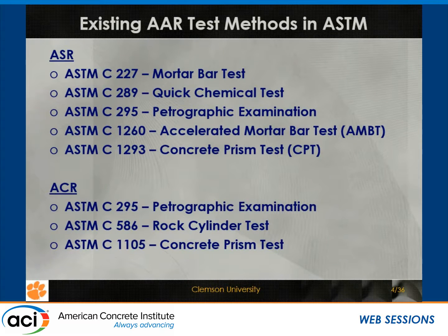And certainly the mortar bar test, which is a faster test, but you have issues with crushing aggregates down from coarse aggregate size to fine aggregates, and doing that, you change the reactivity of aggregates dramatically. Most of the aggregates, you tend to increase the reactivity with a decreasing particle size. But there are certain kinds of aggregates that actually show the reverse trend, where with crushing it finer, you lose the reactive component and you end up less reactive with crushed material than the coarser material. So all of these manipulations that we do to fit into our test methods alter how aggregates show up as being reactive or not in the real field structures.